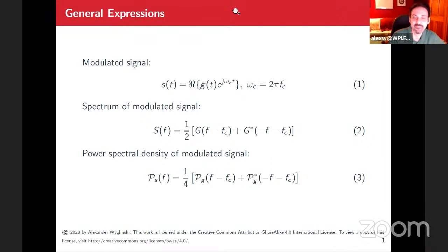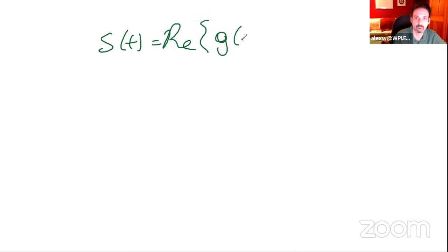I'm going to iterate this again because I think this is going to be the last time we're going to be looking at these equations. So just one last time, because later on when you're designing or using modulation schemes, and you want to convert between the complex baseband and the passband, this is the expression you'll always be using, right? S of t. This is the mapping function of some message signal. Okay.